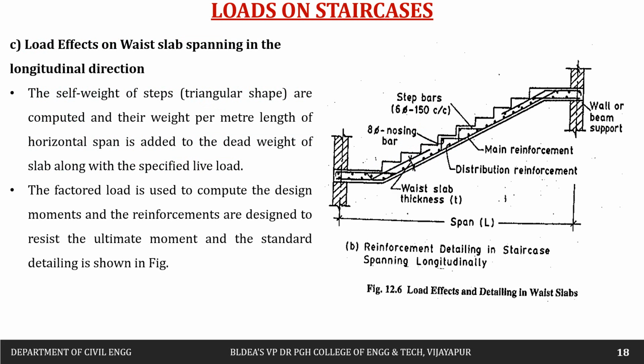For that loading, we calculate the dead load of the slab, of the riser and tread triangular portion, plus the floor finishes, and we take the live load. For this, we calculate the moment. Then we design the reinforcement, and the detailing is done in this way.